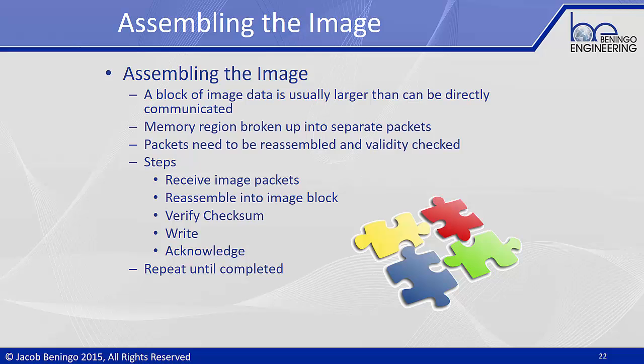This process is going to repeat over and over until every little piece of the application has been downloaded to the microcontroller. In the event that anything goes wrong, you want the bootloader to be capable of NAKing, or not acknowledging that it was successful, so that you can then have the GUI tool resend the data and then hopefully properly recover itself and store the new data.